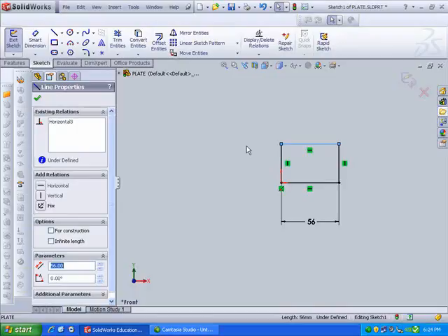The designer of the plastic part did not have a fully defined sketch, and so when our designer was in there messing around pulling components off this, somehow he must have opened a sketch or something and moved it, so the lugs were no longer symmetrical.